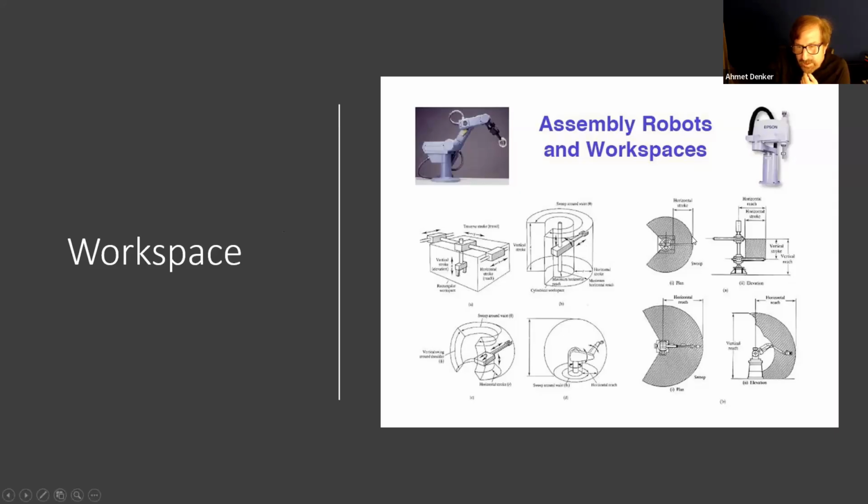Now to cover this partial circle, I need a radius, but I need to change this radius. So I want to cover anything inside this. To change the length, we need a prismatic joint, but also I need to change the angle. To change the angle, I need a revolute joint. So with 2 joints, I can make a robot which covers this.